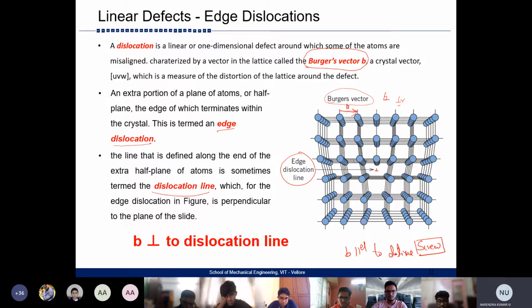So please understand, previously I was talking about point defects, but when I came to this linear defect, I was not using the term defect so much, but rather I was using dislocations. Whenever we talk about linear defects, we use the terminology of dislocation. Why dislocation? Because it is nothing but the plane on which the atoms are going to move. A whole series of atoms are going to move. That's the reason the dislocation term is more important with linear defects. So if you are able to move the dislocation, that means your material is ductile. If you are not able to move the dislocations, or the dislocations are stuck or pinned, that means your material is becoming brittle. So this is how the ductility or brittleness of the material can be described.